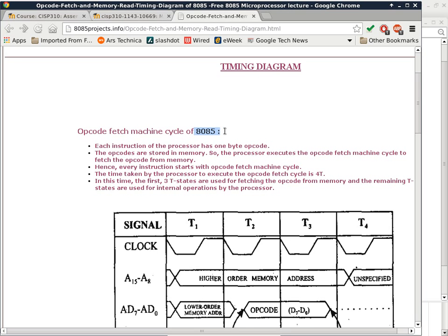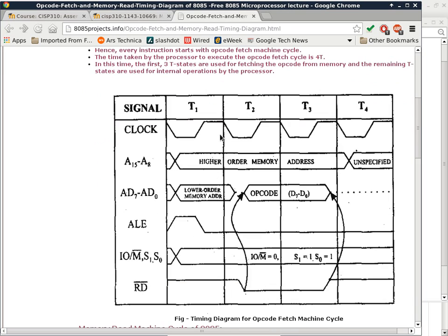So this is what we call a timing diagram. In the diagram, we can see this one is kind of unique because it is sharing 8 pins. Eight pins on the processor are shared between being a part of the address bus and also the data bus. It's done so that they can save traces on a circuit board. This is back when a 3 or 4 layer board is considered kind of expensive and difficult to manufacture.